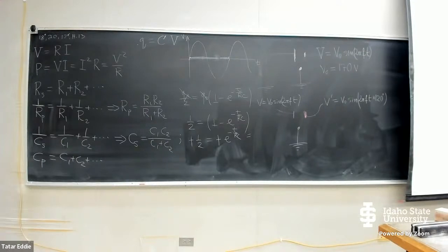So look, the voltmeter measures the different heights of two points. And in order to detect those two different heights, you have to touch those two different points that you want to measure. They are different potentials. In other words, the voltmeter has to be connected in parallel, for example, here, parallel to R2.